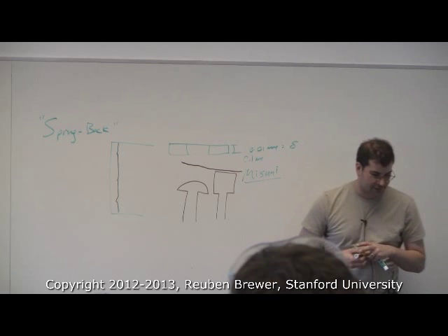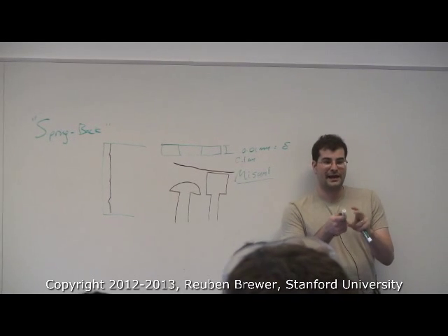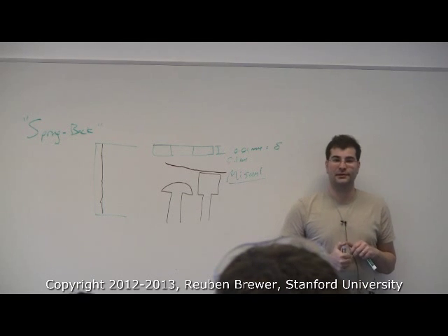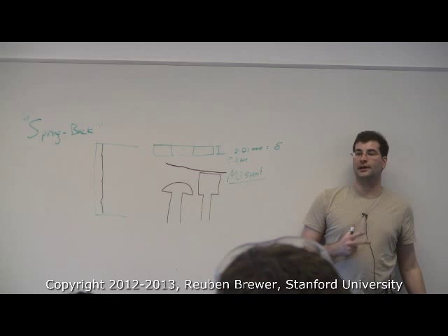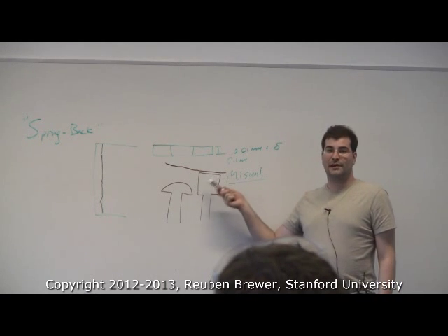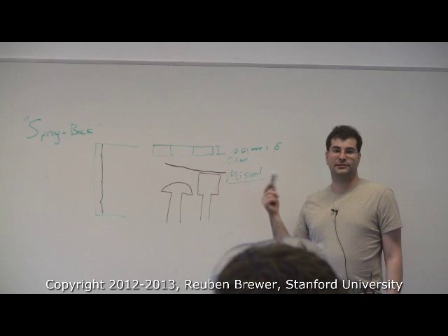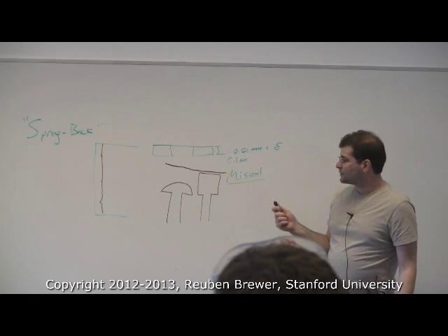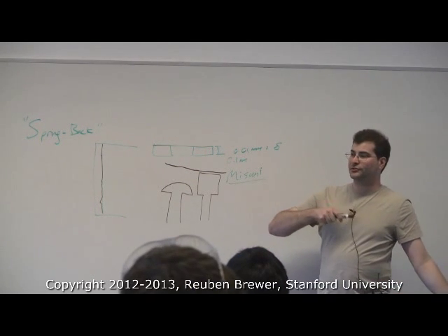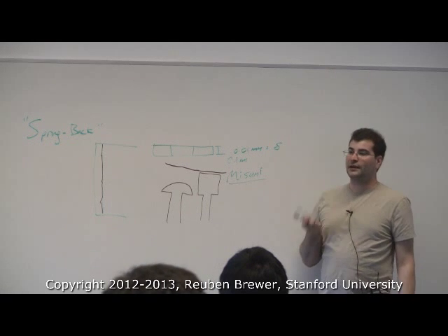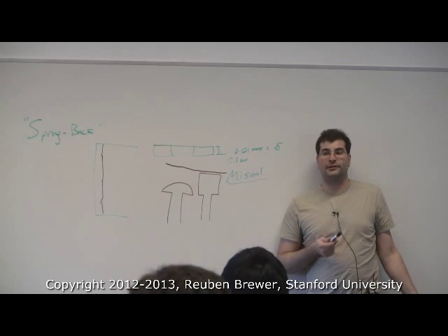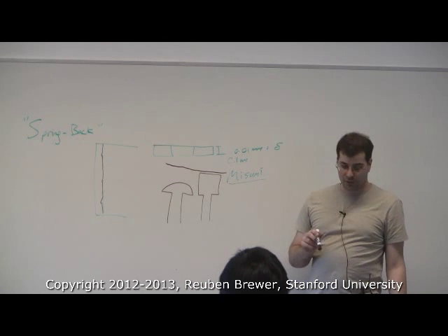Anytime you're assembling something, I want you to look at your CAD. The CAD is open. You're looking at every single part and verifying. If you have 2 or 3 parts, it's not such a big deal, but even by lab 2, we had people using the wrong dowels and the wrong screws, and you only barely got lucky. Now, if this were metal and you didn't get lucky and you ruined your parts, then that would be very bad. So asking the guy next to you or the girl next to you what screw you should use is not adequate, because they might not know. Asking the machinist who's working on your part is not adequate, because they definitely don't know. So you need to have your CAD open.